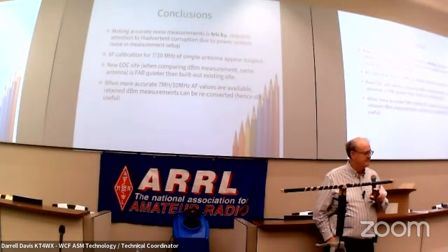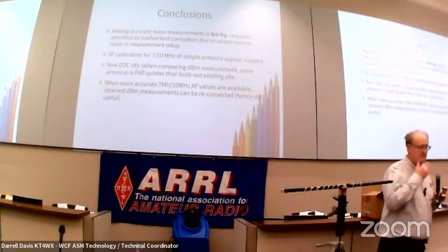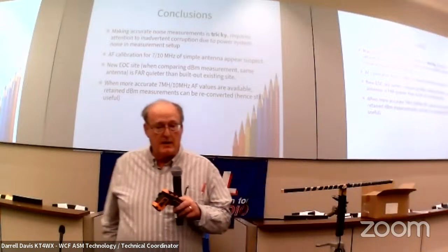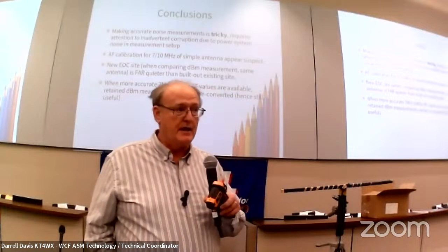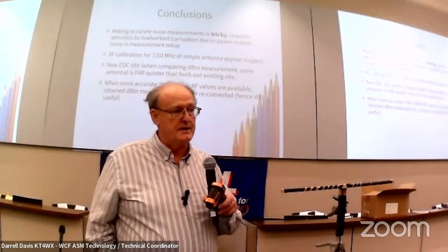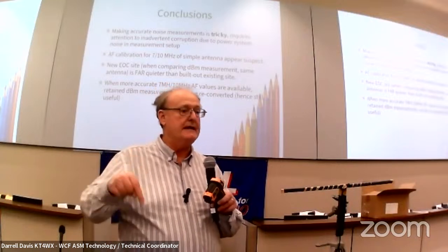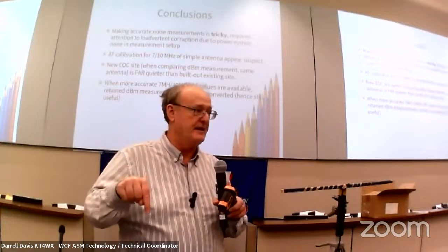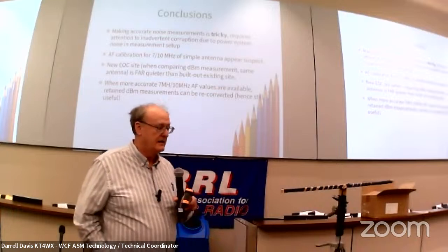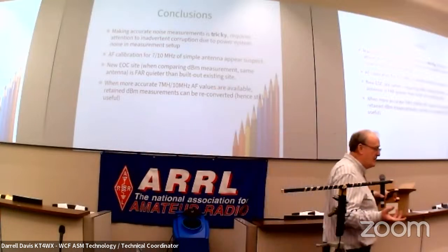I think so. So, I mean, I suspect you get pushback from suppliers. Yeah, because they're probably going to have great trouble meeting this. First of all, they're going to measure it according to FCC standards, which is not good enough. And we want it measured in situ at our facility. Do you still meet Class B standards the way we're going to install it? And if you don't, we're going to have problems. Now, how do we get around that? How do we mitigate it?